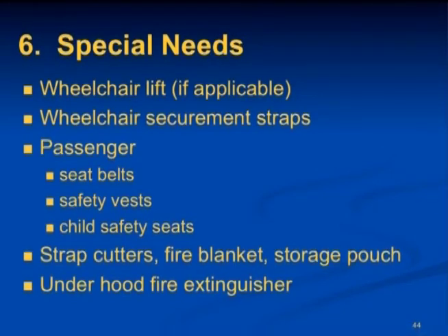Safety vests should be checked for cleanliness and condition. Child safety seats should be checked for cracks in the shell. Internal harnesses should not be twisted or frayed, and the covers should be clean and sanitized. Follow the Federal Motor Vehicle Safety Standard and best practice for installing safety seats in the school bus. The child safety seats should be fastened to the seat frame with seat belts installed and attached to the bus frame seat, and make sure that they bite into the seat. The seat should be secured tightly to the bus seat with only about 1 inch of play.